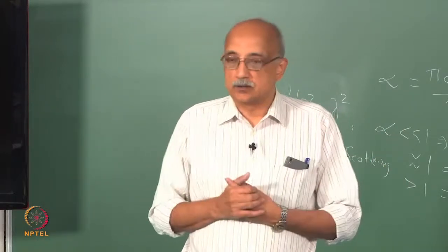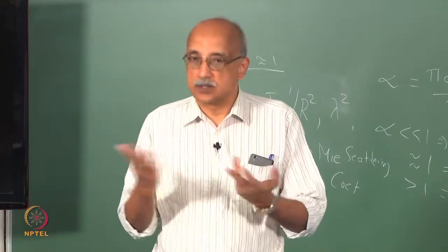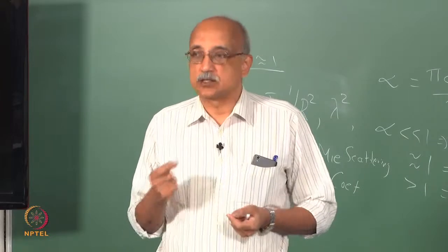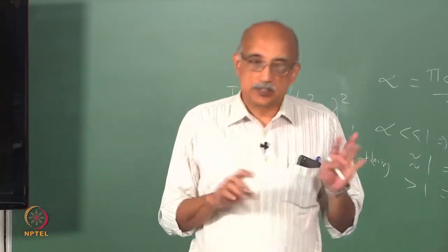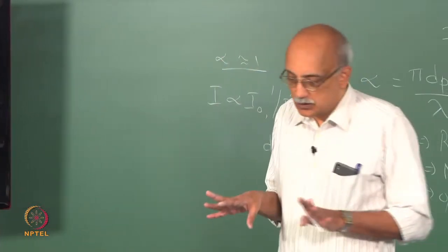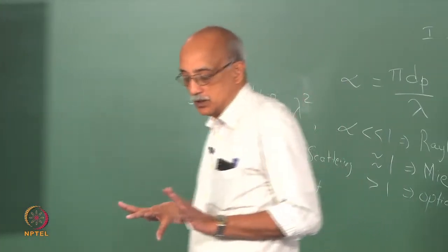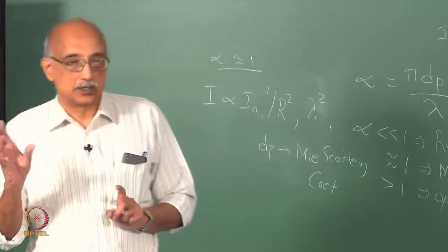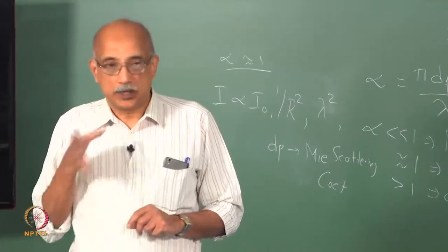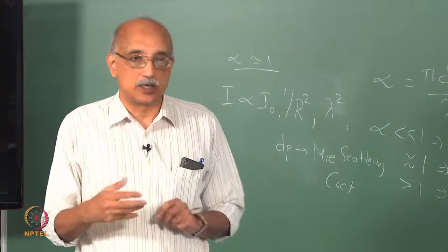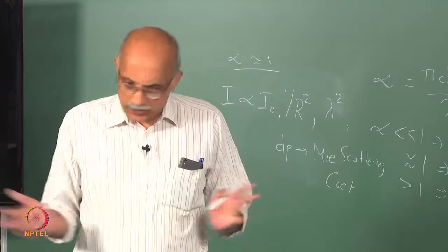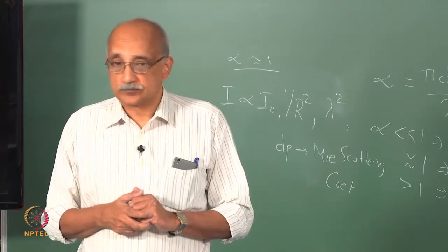In order to do that, we have to use what are known as, I was mentioning at the end of the class last time, particle counters and particle size analyzers. The difference between a particle counter and a particle size analyzer: a size analyzer is a simpler instrument. It does not give you counts, it does not tell you how many particles are between various size ranges. What it gives you is the mean statistic, what is the average size of the particles in the suspension, what is the standard deviation and so on.